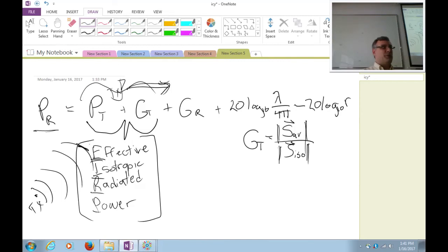In fact, one of the ways to view Maxwell's equations is almost like a low-pass filter in free space. It smooths over all the differences in wobbling, in oscillating propagation. The lower the frequency, the more the smoothing. So when we say an antenna has an aperture over which it gathers power, it's okay to approximate it as an actual physical aperture, but recognize that the edges are going to be fuzzy. It's not like it gathers 100% of the power from the plane wave, and then beyond the edge of the aperture, it gathers 0%. There's a little tapering and some oscillations that go on along the fringe.